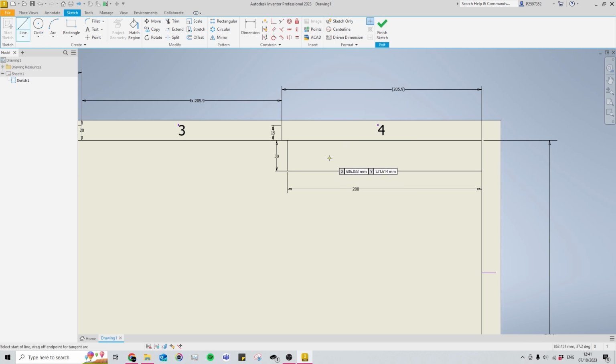Each area here is for the revision letter that it is, the date of the drawing change, the initials of the person who made the change, and the description box in order to make note of the changes that were made within this revision. Some companies also use a change number box too, so if that's you, you're going to need to add another box also.